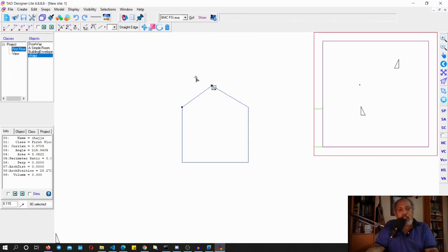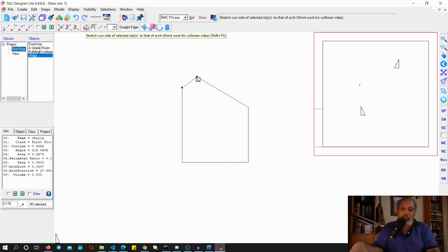So now what I'll do is that I will take the architect here and I'll stretch that edge. So it will actually go further towards it. The side angles do not change. So, oops, sorry, I used the wrong command. I'm sorry. I used the F5 command. I should use the Shift F5 command. So Shift F5 or this particular button here, and you can read the hint which is given, that will stretch that particular edge over there. So I press this.